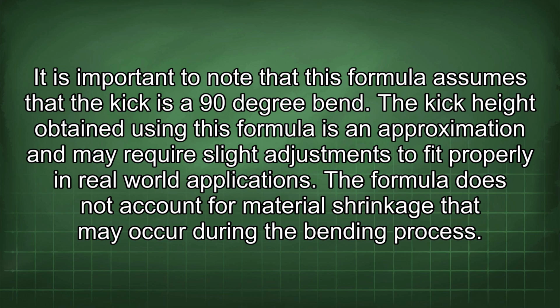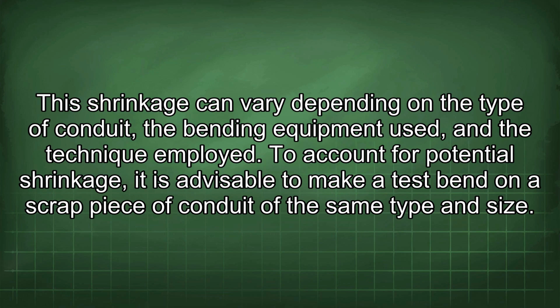The kick height obtained using this formula is an approximation and may require slight adjustments to fit properly in real-world applications. The formula does not account for material shrinkage that may occur during the bending process. This shrinkage can vary depending on the type of conduit, the bending equipment used, and the technique employed.